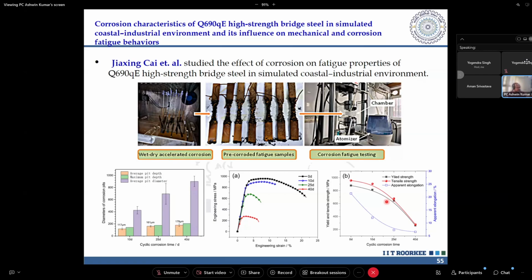If you design a bridge for a particular steel grade and it undergoes corrosion and is not being maintained properly, then your stress range is also going to increase because of the thickness loss of your member. Maybe you wanted the stress range to be within the yield strength of the material, but if you suddenly get such a high reduction, it might even go into the non-linear range, right? So there is a high risk there.